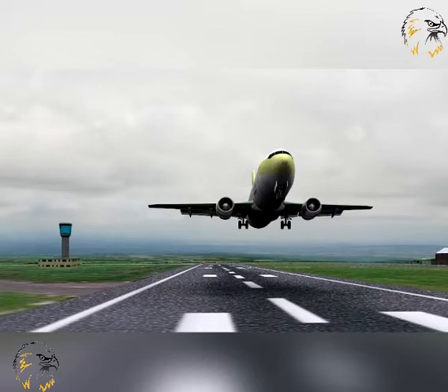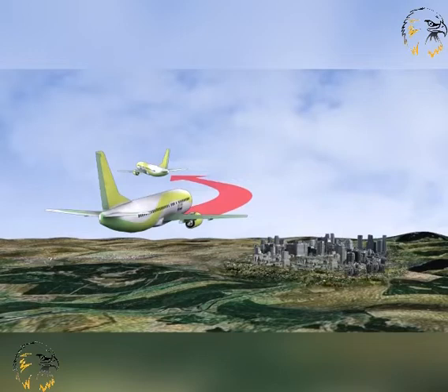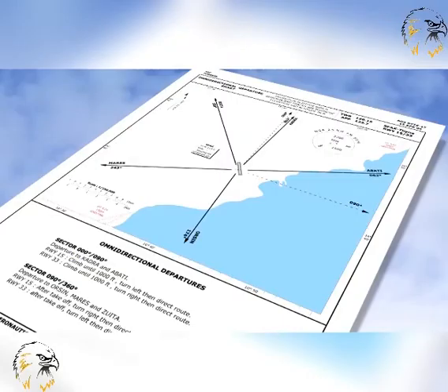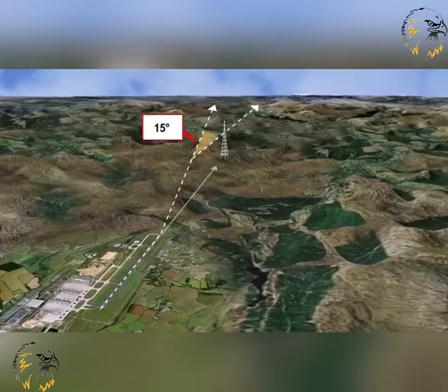the departure route. From the point of view of aircraft operators, the use of in-cockpit systems, such as Automated Takeoff Thrust Control Systems, ATTCS, and noise abatement procedures, need to be taken into account as well. Where no suitable navigation aid is available that can provide specific departure track guidance, then the criteria for omnidirectional departure plates are defined. Wherever possible, a straight departure will be specified which is aligned with the runway. If, to avoid an obstacle, a turn of more than 15 degrees is required, a turning departure is constructed.